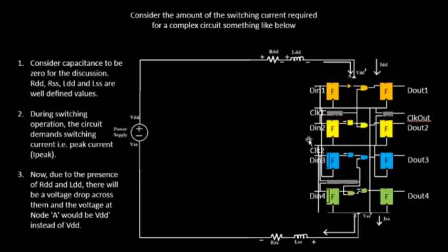Let us consider this piece of circuit is a part of any of block A, block B, or block C that we saw just now. In our example, this is the main circuitry, but let's consider this is a part of block A, block B, or block C. Whenever this particular circuit switches, for example, if you take this particular AND gate, when the output of the AND gate switches from logic 0 to logic 1, there is an amount of current demand that it needs.